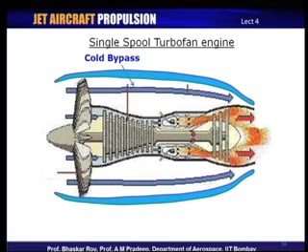And as we have just seen, this cold jet would have a lower velocity, the hot jet would have a higher velocity, and two of them together would produce the thrust, and the average velocity of that would be lower, and as a result of which your propulsive efficiency is going to be higher, and the benefit accrues in the form of SFC.